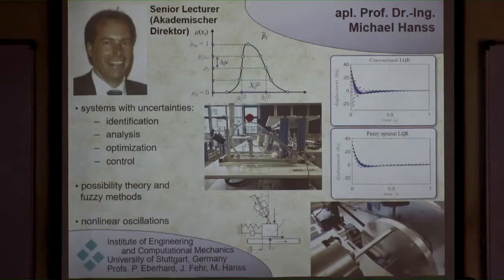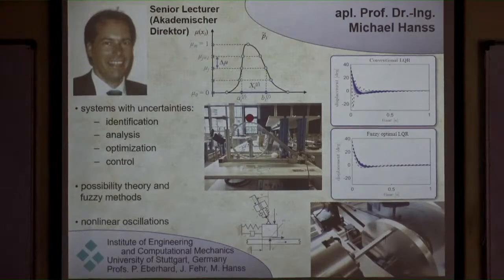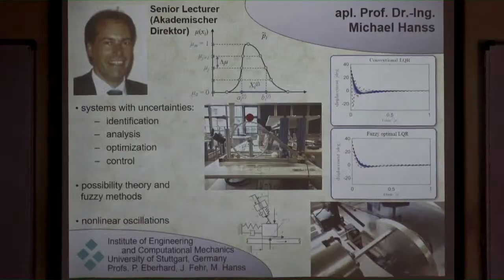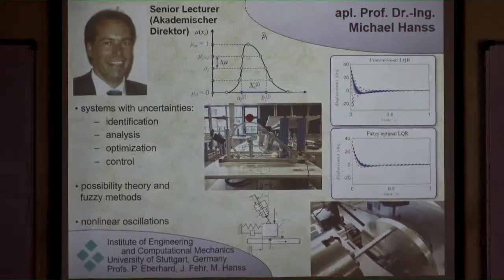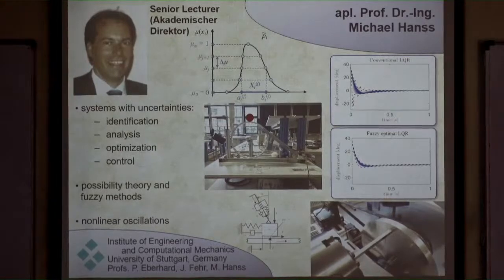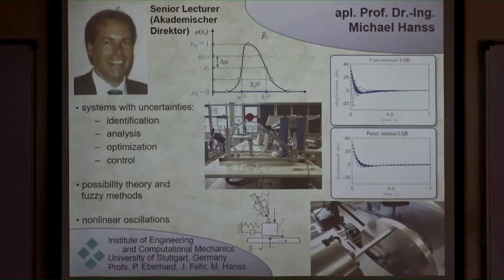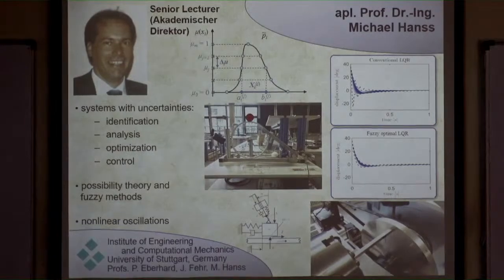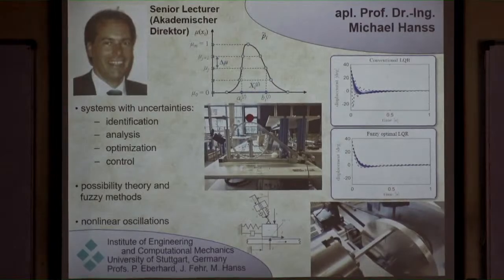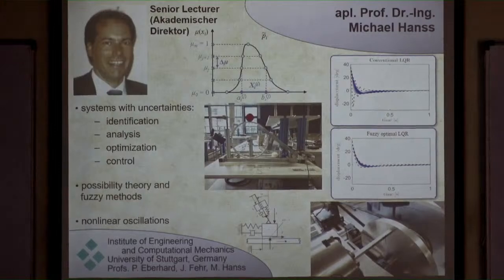And then everything was set up, everything was working, and then somebody in the company had a bright idea: let's put in some oil which has a lower viscosity. If the viscosity is lower, you need less energy, it's rotating faster, everything is beautiful. But suddenly this was a very sensitive parameter. Adding this oil with the lower viscosity completely damaged the centrifuges, and within a few days all the centrifuges were damaged. Which is good for peace, but not so good for the company which wanted to produce these things.